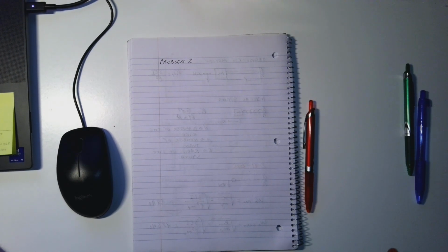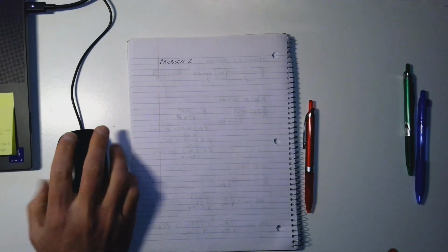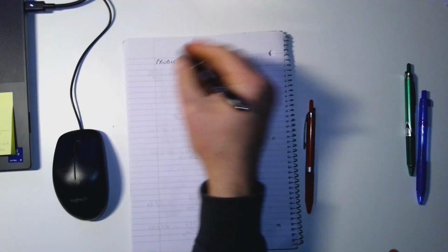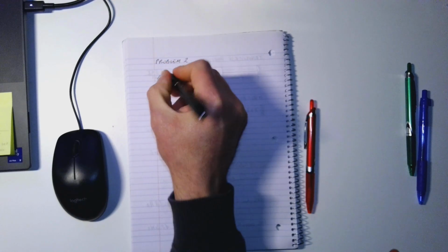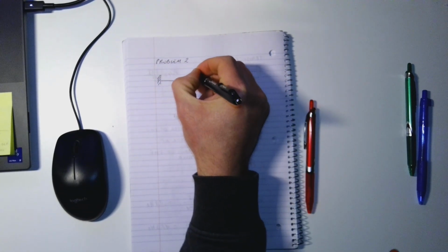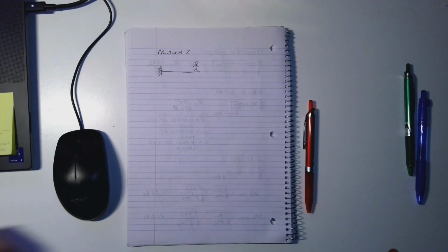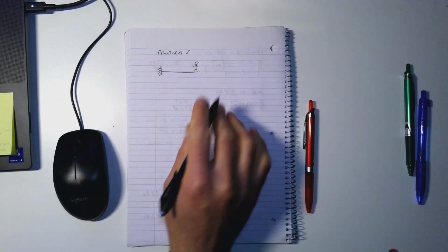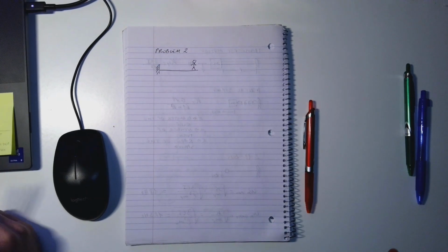Exactly. In this case, we need to just use the exact same equation that we used before, because it's the same type of motion. It's also a transverse motion, so we can model our diving board. The person would be here, to be the diver, and we know the mass. What we have to find is the value of the flexural rigidity. So the flexural rigidity is the product between Young's modulus and moment of inertia.